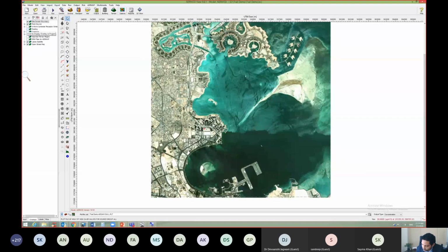It can, yes, it is available from the stack monitoring also. It is available from the supplier of the DG, who will also guarantee the emissions, and we can also find out on the product sheet of the diesel generator what the emission rate would be. In addition, we can also estimate the emission rate from the stack testing that is done for a similar capacity of diesel generator.